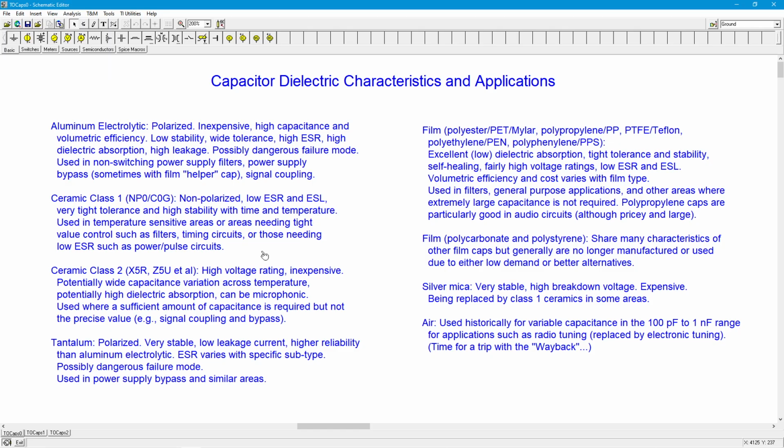In other words, we're talking tolerances of maybe minus 50% plus 100%. In other words, you can get 2-to-1 variations based on the nominal, right? So the thing says X farads, but you could have twice that or half that. Okay, they vary all over the place with temperature.